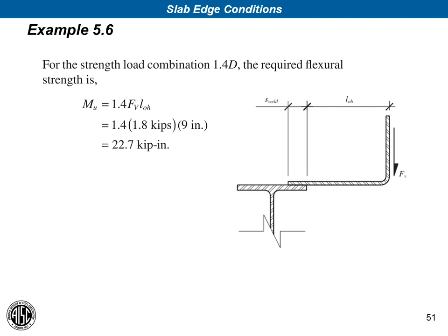In this case, yes. But I think the example problem that we had was specifically for a roof example. So I don't think that we had concrete in this example, though I could be wrong about that. I'll have to go back and check my slide. But if there is concrete on the deck, then you would have to consider the concrete load as well. I take it back. There is concrete in the deck, so it should be included in the analysis of the bent plate and in the welds. So we'll pick that up for the next revision, Nate. All right. That's no problem.